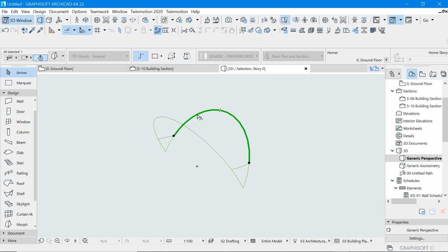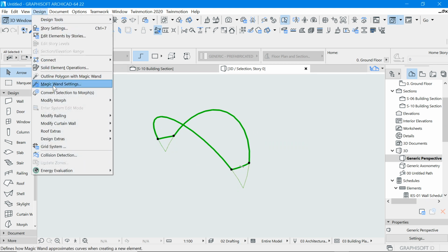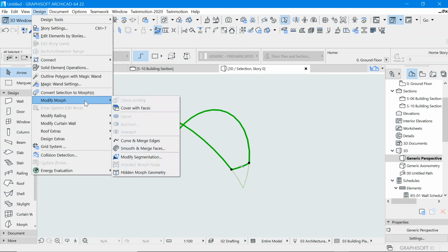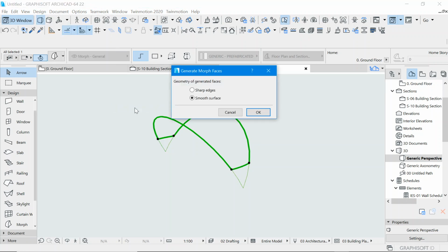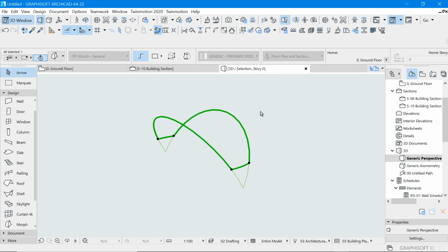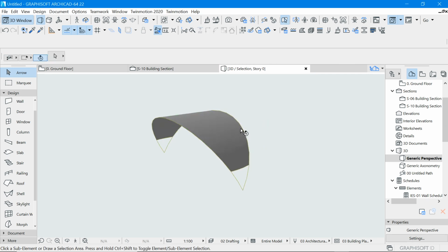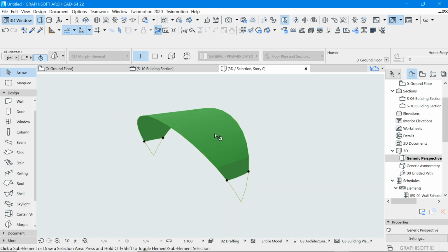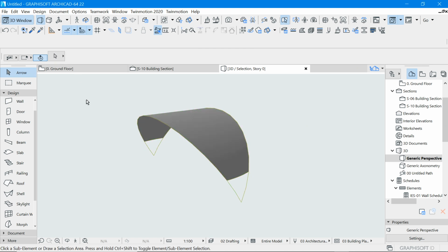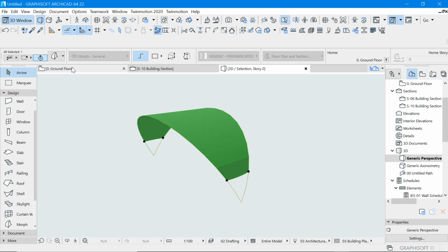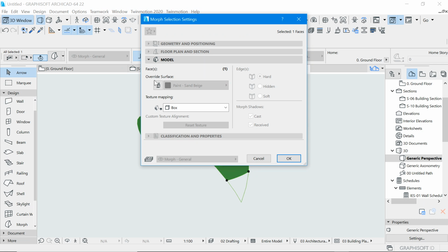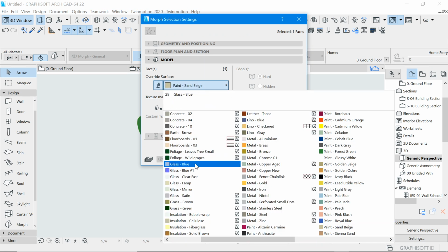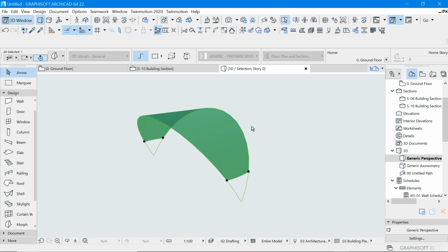In there, pick what you want to turn and cover the surface. Now once I've highlighted those 4, go to design. Under design, I say cover surfaces with a smooth surface. That will be covered. So once this is covered, remember I'm still in edit mode. I can change the material of that. Can give it like blue glass.